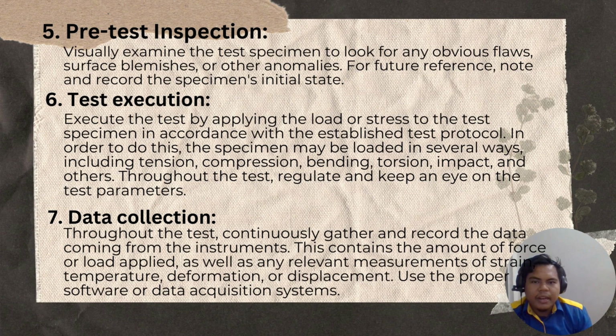Visually examine the test specimen to look for any abuse, flaws, surface blemishes, or other abnormalities. For future reference, note and record the specimen's state.